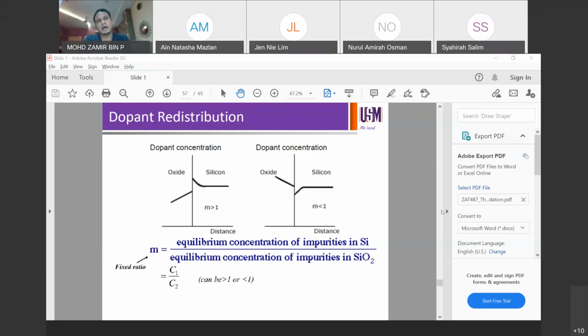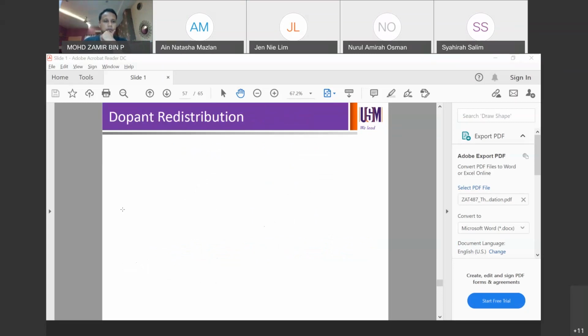So if you have a dopant profile, or dopant with some concentration, before the process, and then you subject the wafers to the oxidation process, the surface is going to experience dopant redistribution during the process. Each of the common dopants that we use for our doping process, we're going to learn about in detail later on, is going to show slightly different behavior.